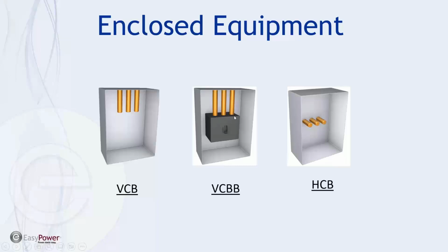In a vertical terminated in a barrier, it can start and travel down, but then it blooms out horizontally, and that's where you get more of an amplification of the hazard. And then the worst case is horizontal in a closed box, where you're staring right at the butt end of the buswork, and worst case, a technician would receive the full effect of the bloom.